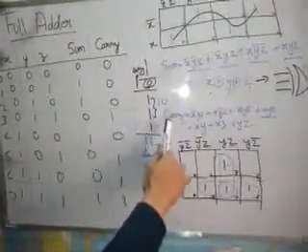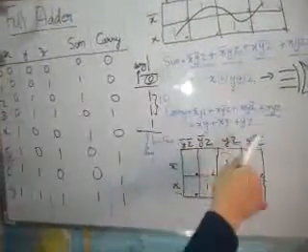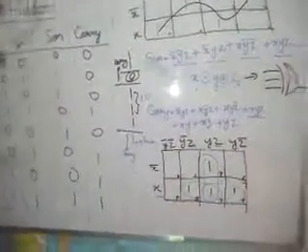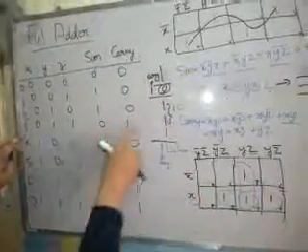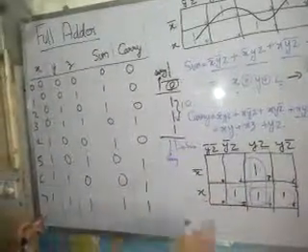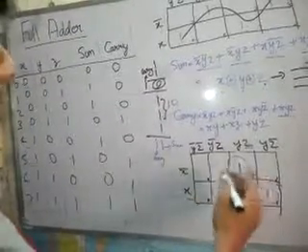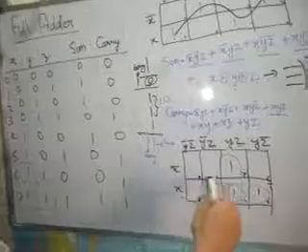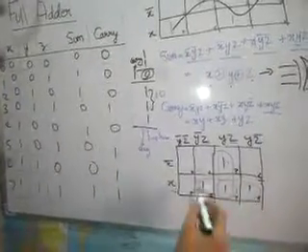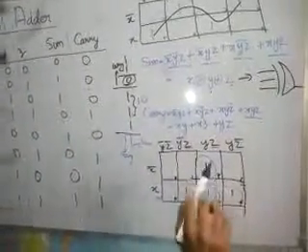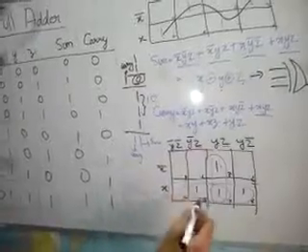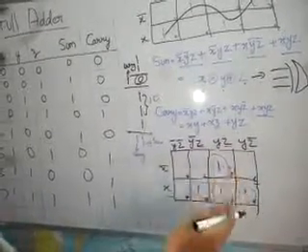So अब हम we will study how to design a carry circuit. Carry circuit, it is simple. We will first substitute ones. 1 is in 3, 5, 6 and 7. Now after substituting this, we need to group these ones. So we are grouping these ones like this, this, this and this. After this, we need to make groups and write equations.